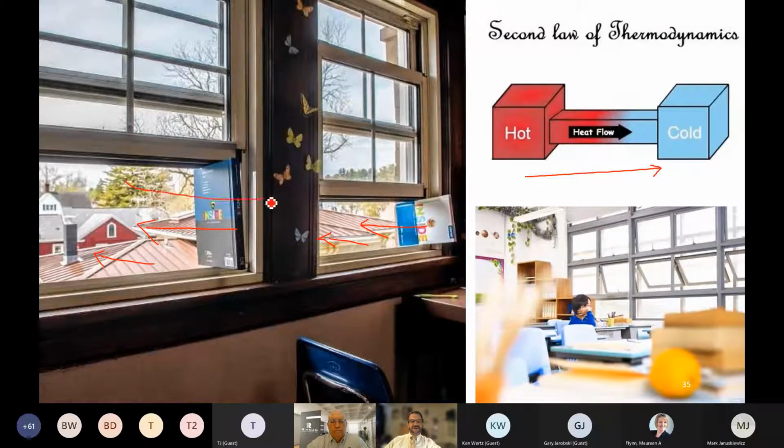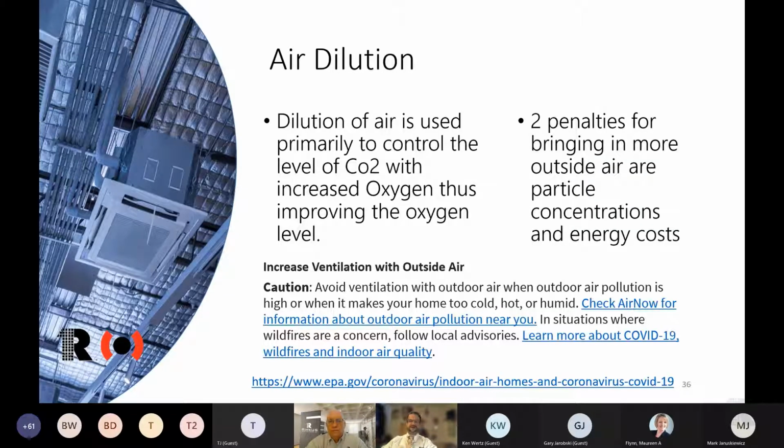What happens is, from time to time, you have air blowing in, you have air changing directions, depending on what side of the building. I've had buildings set up where we had to have absolute 100% control on the rooms as far as pressurization is concerned, and the air would change direction and positively pressurize a room way beyond, 10 times higher than we thought we could control. It is a variable that's really very difficult to control unless you're setting up fans inside here. So it's not a one-stop works-perfect measure. It can be done, and it may need to be in some cases, but we need to know the implications of it.